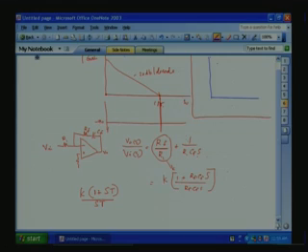the T here. So, if you see here, when it comes to the frequency 1 by T, the effect of the zero in (1 plus ST) by ST will come into picture and it will go like this. For the phase, because of the integrating part it will start from minus 90 degree and slowly go to 0 here.